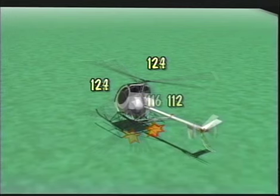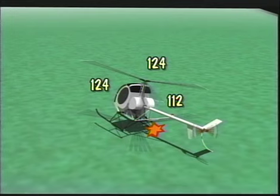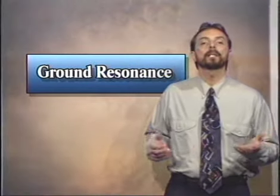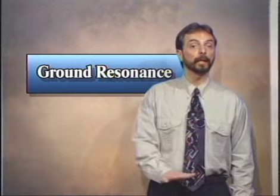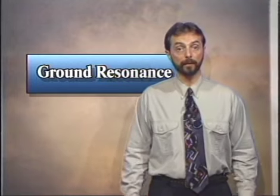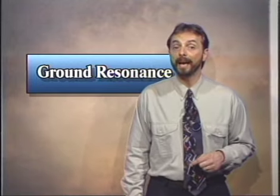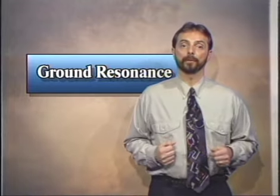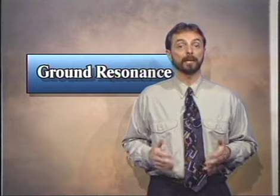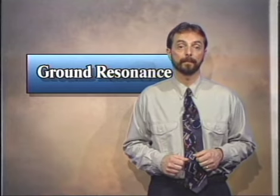Then the other landing gear may strike the ground, causing the blades to go even more out of phase, aggravating the imbalance. Because this hazard only occurs from contact with the surface, the aircraft is typically in a low altitude, low airspeed configuration and using a high power setting. Sending lots of power to an out-of-balance rotor system is a surefire way to make the aircraft start shaking violently.